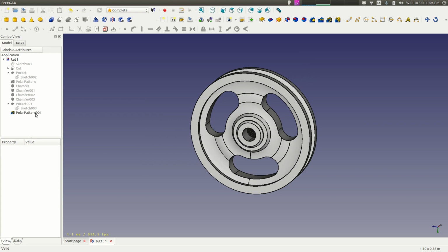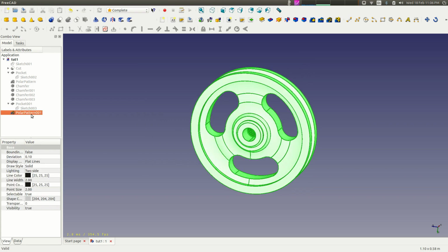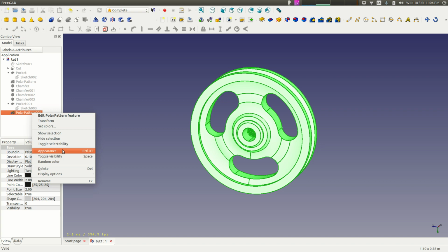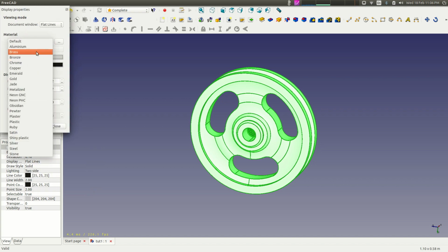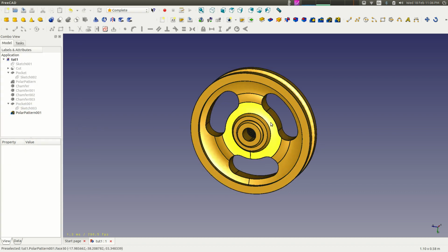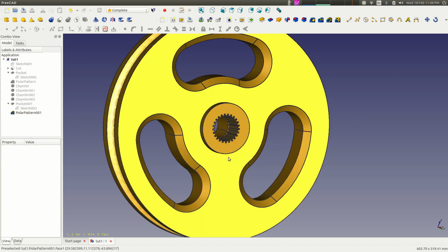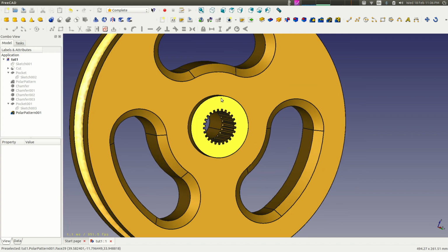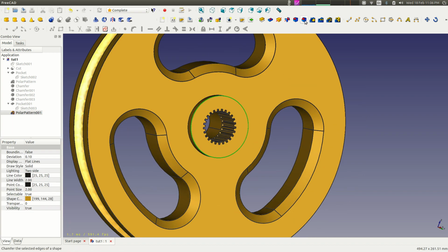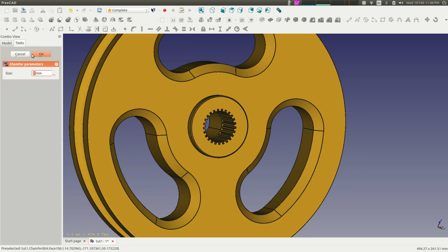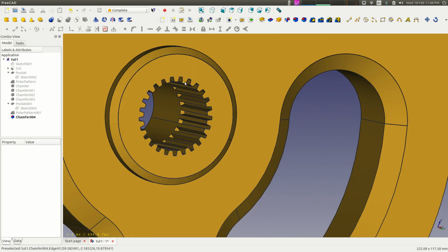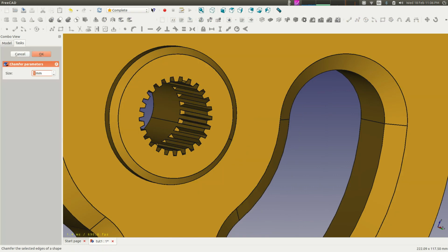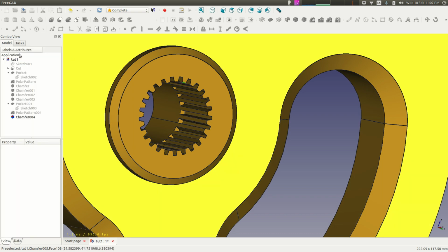You can also edit the color of it. So if you side click on here and go to appearance, you can select, maybe you wanted to make this out of brass. You know, give it kind of a brass color. Give you all your splines and stuff, and oh, maybe that edge needed to be filleted or something. You know, whatever you need to do. Maybe that one edge needed to be filleted, or you could get them all or something like that.